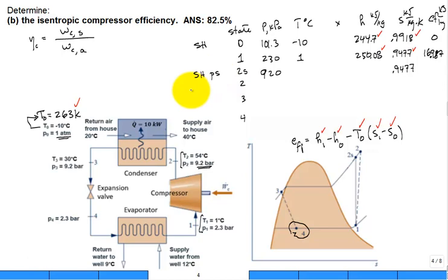Calculate the temperature if you want it, and calculate the enthalpy. The enthalpy is the property we really want. This comes in at 279.96. Yes, interpolation, but oh well. And just for kicks, the temperature would be 48 degrees C.